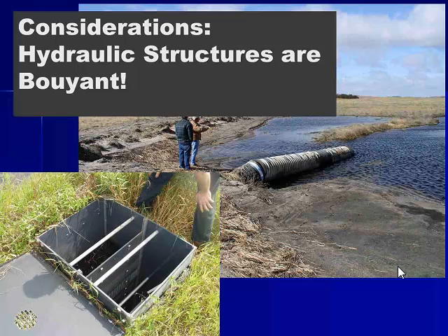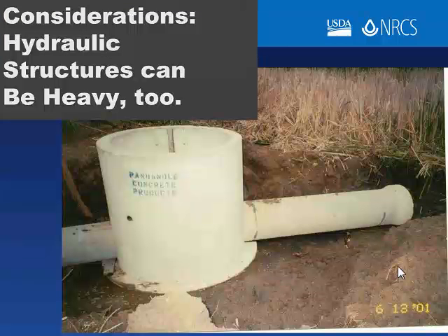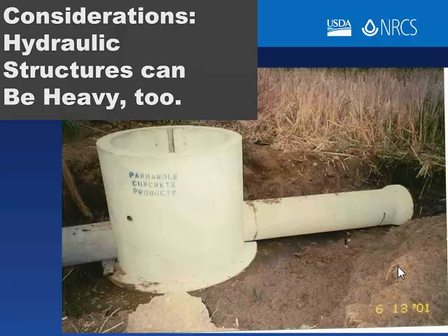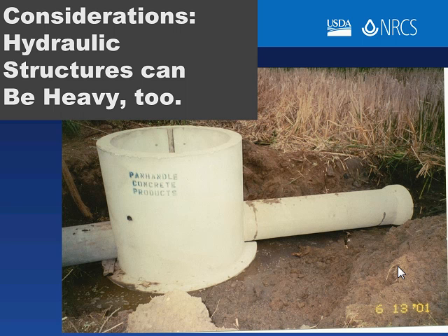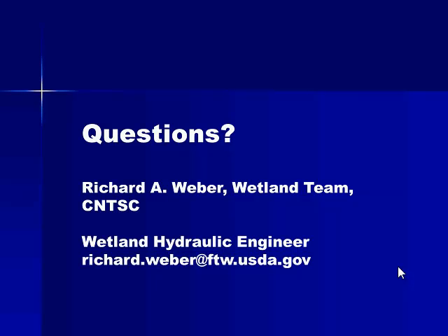And the reason they don't fail any more than they do is because they typically are held in place by a drawdown tube and a principal spillway. That buoyant force is putting stress on those connections that we typically don't anticipate. Conversely, here we have a stop log structure out of precast concrete. Obviously, very little problem with buoyancy, but they're heavy. And wetland soils are typically pre-consolidated, saturated, and so we also have settlement and consolidation of those foundations. And with that, Bill, I can take whatever questions we've got.